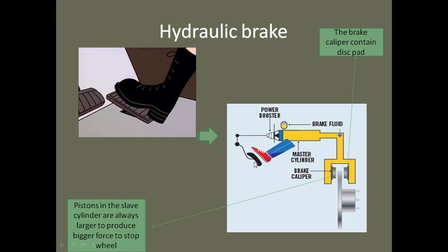In the car, we have the braking system that you see. They are all connected with links to a piston inside a cylinder. The cylinder contains brake fluid. Brake fluids are special fluids that cannot be compressed easily. On this side, this cylinder is called a master cylinder because it holds the master piston, the piston that exerts the pressure on this side.